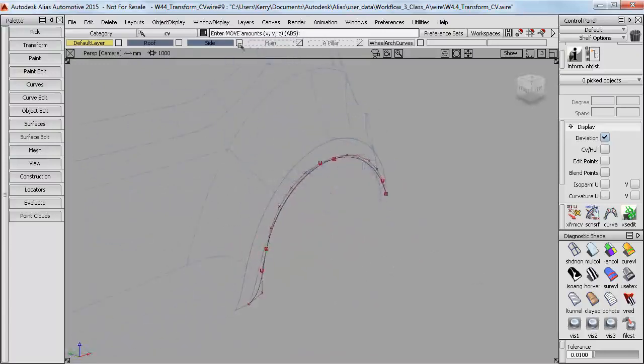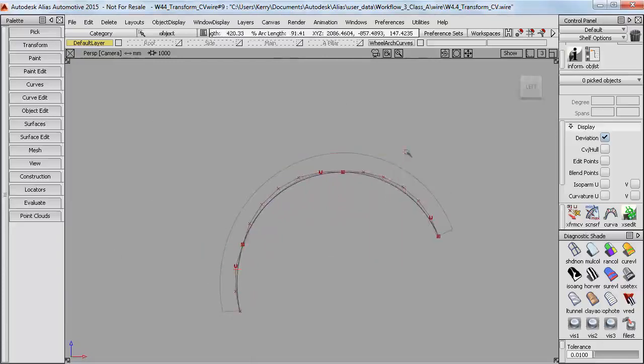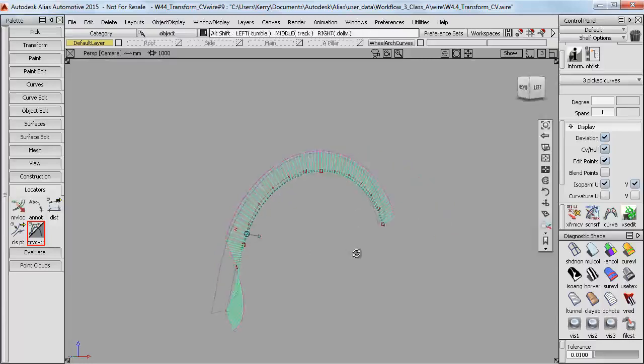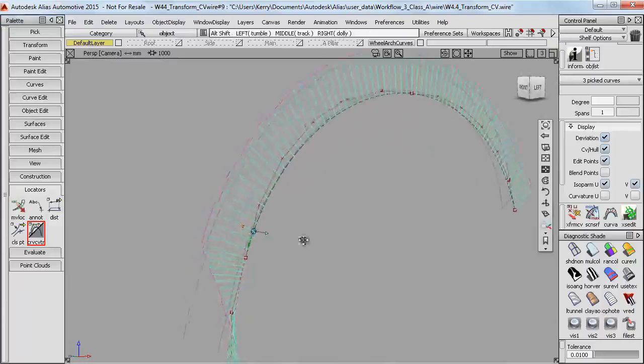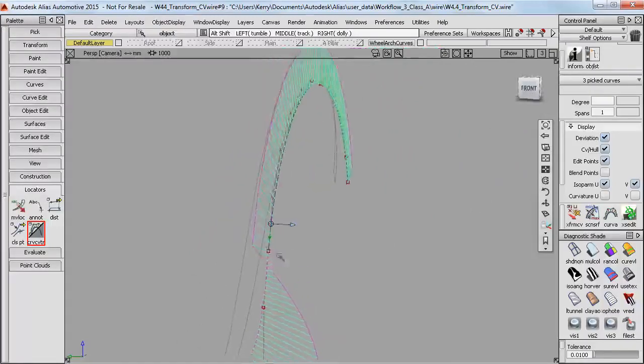So I'll turn off the surfaces that I'm not using, and then you can see this template surface which is from Mike's concept design. What I've started to do is build more precise curves for building the final quality data, so true arcs and aiming for G3 continuity. I'll start at this end, and you can see that my curves are flat to begin with, so I just need to start tucking it in here.